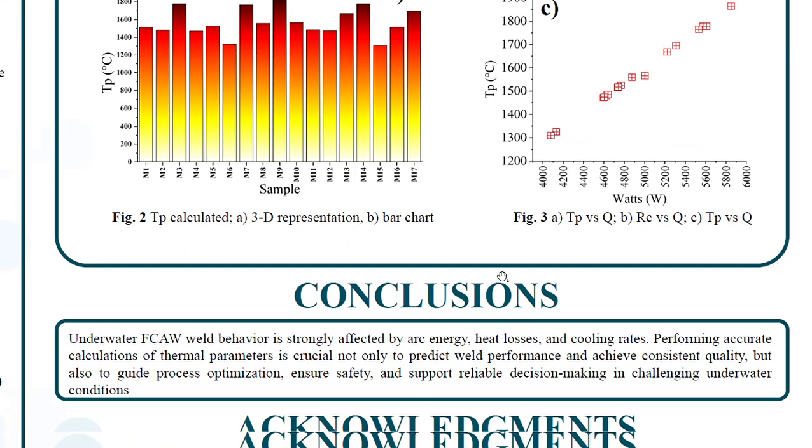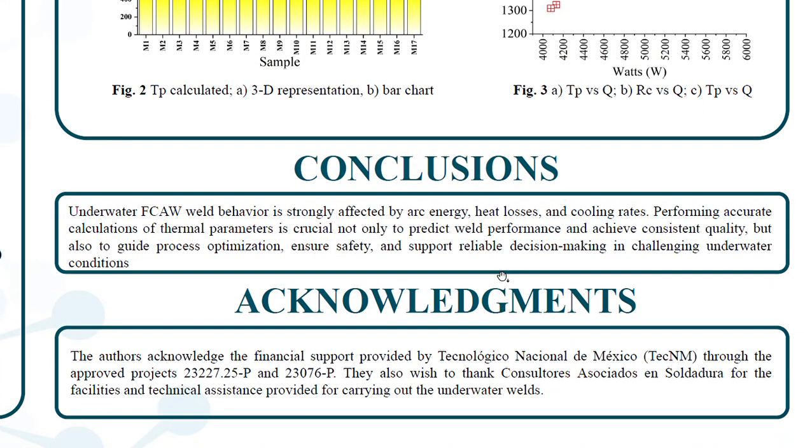In a general form, as a conclusion for this work, the behavior of underwater FCAW welds is strongly influenced by arc energy, heat losses, and cooling rates. Also, accurate calculation of thermal parameters is crucial, not only to predict weld performance and ensure consistent quality, but also to guide process optimizations, improve safety, and support decision making in demanding underwater conditions.